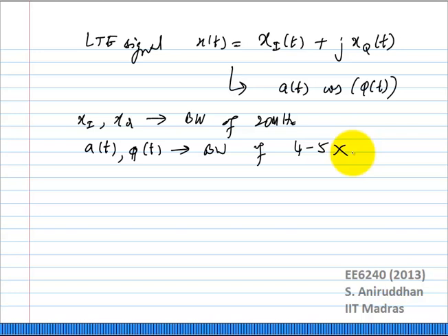The exact factor really depends on what kind of modulation you are using, but it is much wider. So now, starting off from a 200 kilohertz signal or a 100 kilohertz signal, you are talking about transmitting a phase modulated signal of maybe 100 megahertz. This is really wide. Okay, and you are talking about using circuits to process these. They will be power hungry. Getting the transfer functions to match over this kind of bandwidth is extremely difficult.